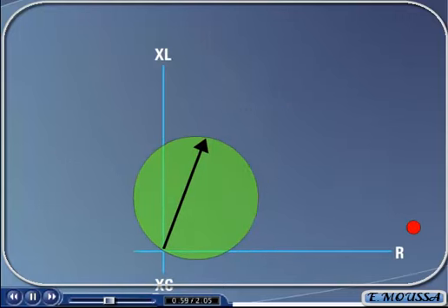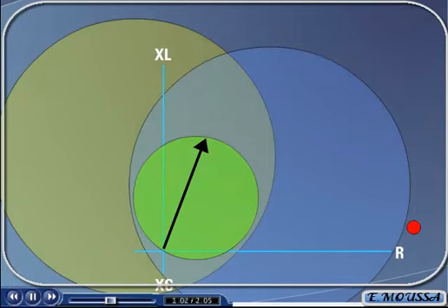This is detected by creating an additional impedance zone located around the operating impedance zones as shown. A stable power swing is detected if the impedance of the system moves into this new impedance zone for an extended period of time. Under this condition, the distance protection will be blocked. If this swing were a real fault that entered the power swing blocking area, it would move very fast through this additional area and into the operating impedance zone. The power swing blocking characteristics must be configured to be much larger than the distance Zone 1 characteristic to ensure a stable power swing is detected long before Zone 1's operating characteristic is reached.